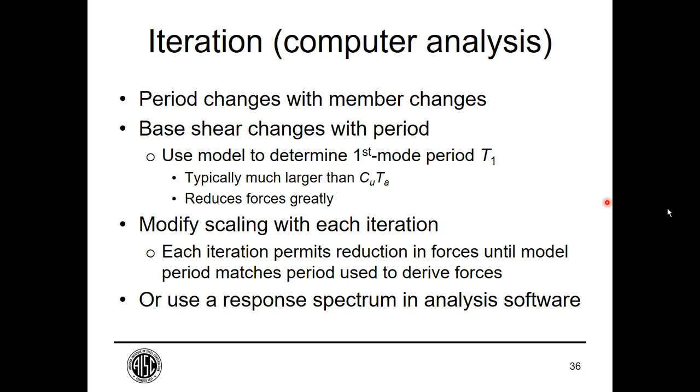And in many software programs, you design to a response spectrum. So the computer program calculates the period and then determines the appropriate force from the spectrum and then calculates the drift corresponding to that force.